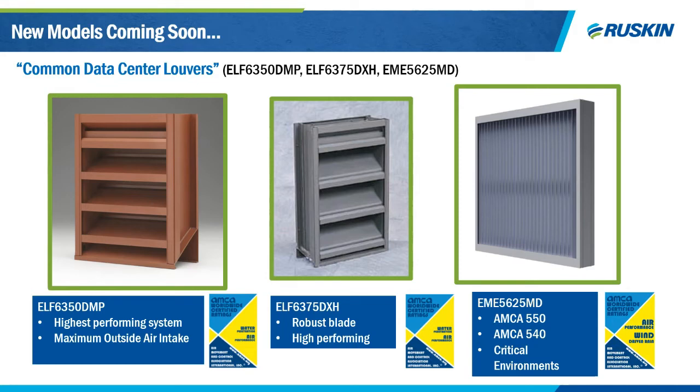So this louver is approved for AMCA 540, which tests your impact resistance, and AMCA 550, which is your high velocity wind driven rain test. It's Miami-Dade certified, as I mentioned, as well as Florida approved. And this model offers excellent Class A wind-driven rain protection as well.